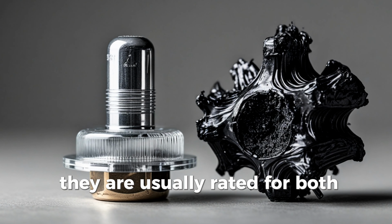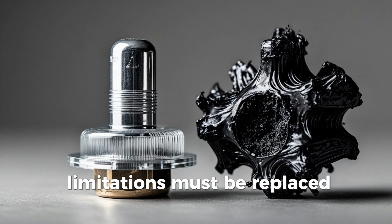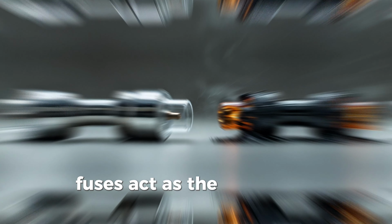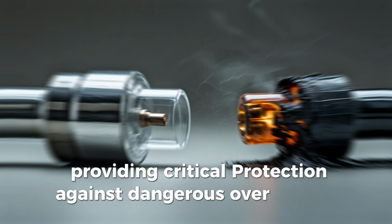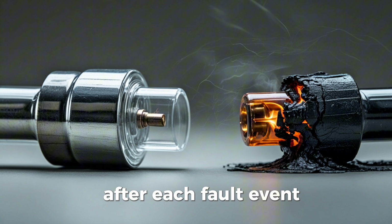They are usually rated for both voltage and current and must be carefully selected to match the motor's characteristics and the application's safety requirements. Limitations. Must be replaced after operation. Offer no indication of the fault cause or condition unless combined with external indicators. Cannot be remotely reset like circuit breakers. In summary, fuses act as the first line of defense in motor control systems, providing critical protection against dangerous overcurrent events. While they offer reliable and rapid protection, the trade-off is that they require manual replacement after each fault event.